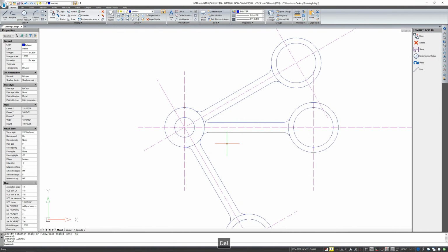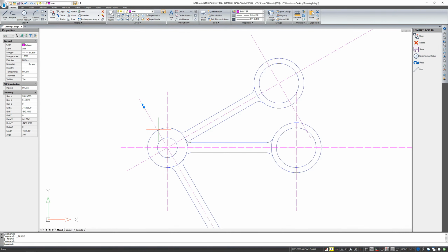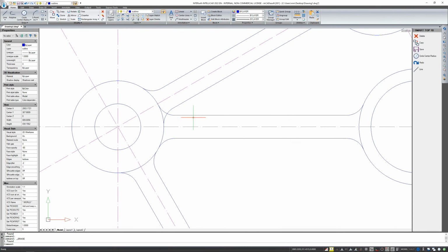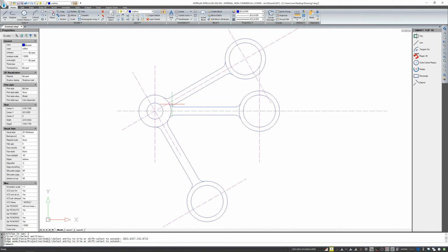That is, between this and this, I have an angle of 90 degrees. These elements overlap. I could use the overkill option for this, but I'm only going to remove this one element at this point to make it okay. Here these elements overlap. One is higher, the other one is lower. So select the cutting element and then the one that is hiding below it. If this element was to be duplicated several times at the same distances, I could use the array option. I'll show the array in another example.